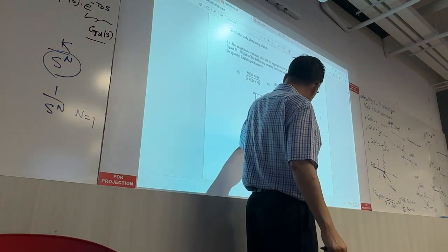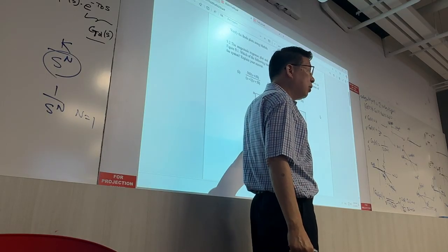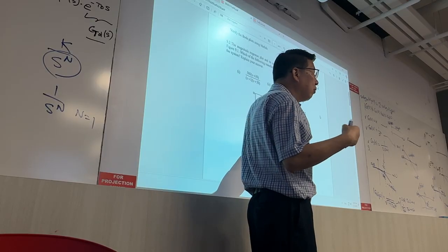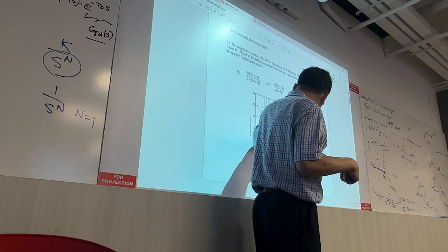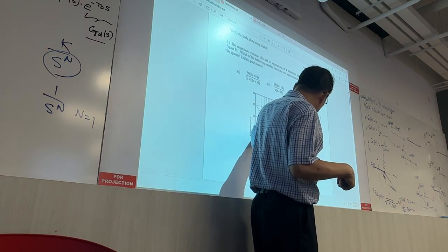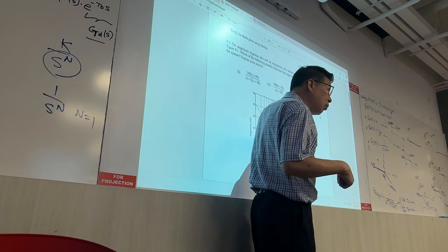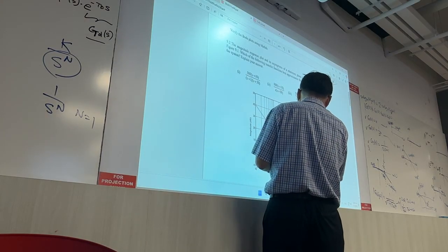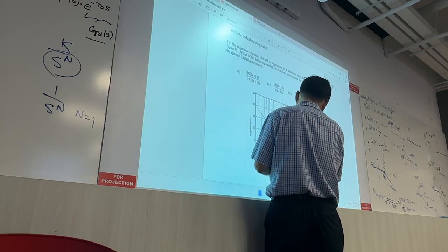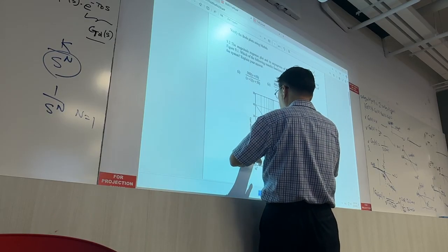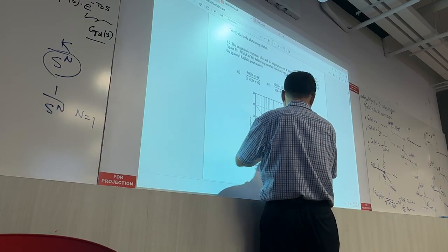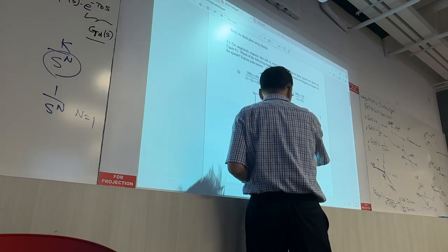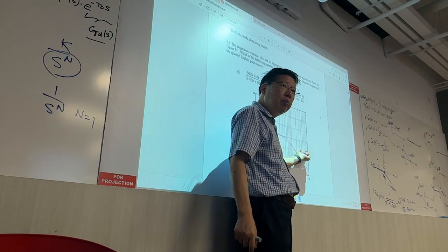At this 10, it's a bend upwards. That means this is due to a zero, something from the numerator, right? And then at this 50 radians per second corner frequency, the slope bends downwards from 0 to this. This means in this 1 decade, it reduced by 20 decibels. This is about 20 and this is 0. So this is minus 20 dB per decade.